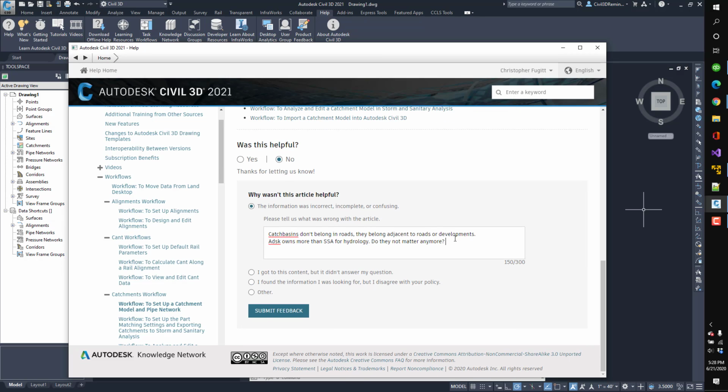And then the discharge point. Pipes usually carry water to the discharge point. And an inlet is upstream of the discharge point. So you have the pipe at the output, and then you usually have an inlet, like 3 or 4 or more pipe run lengths up there, and that's where your catchments go. And then the catchment catches the water and takes it to the pipe to your discharge point. The end of your catchment isn't at the discharge point, usually, other than your overall one.